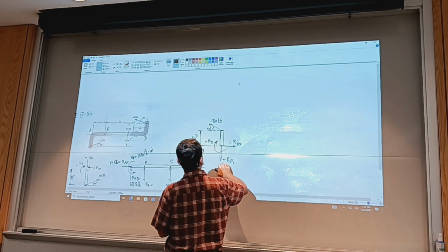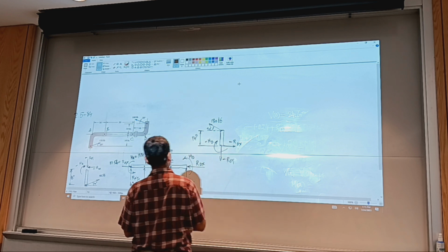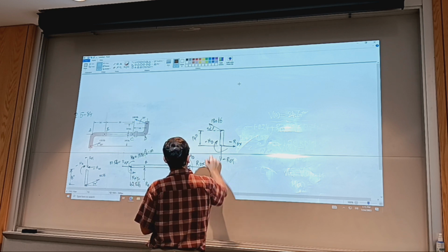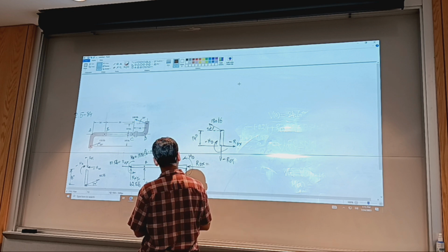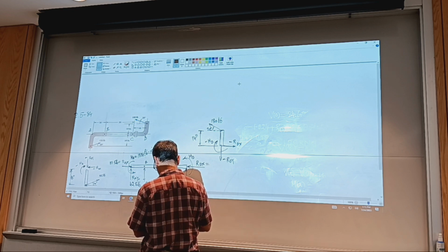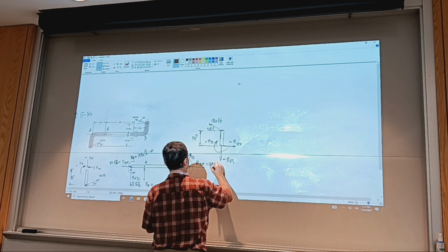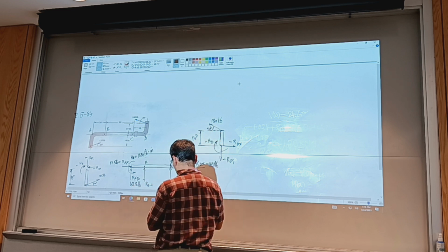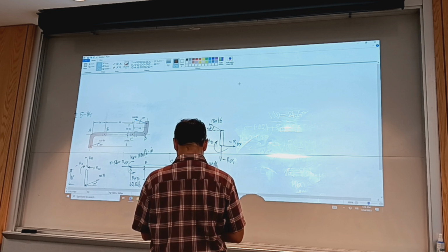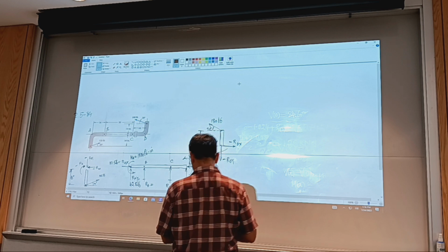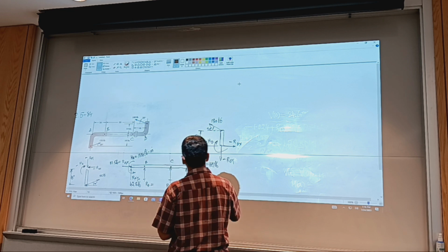So the horizontal, the x component of RDX that shows on this graph is going to be 180 times cosine 20, which equals 169.1 pounds, and the one that projects with sine, 180 times sine 20, equals 61.6 pounds.